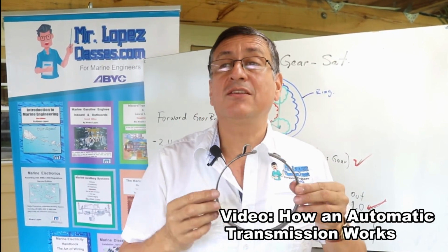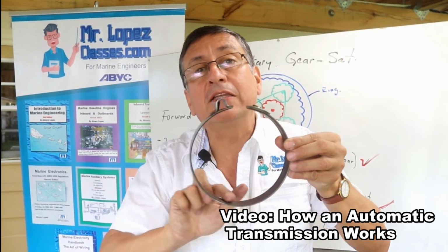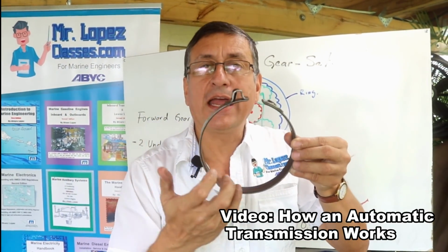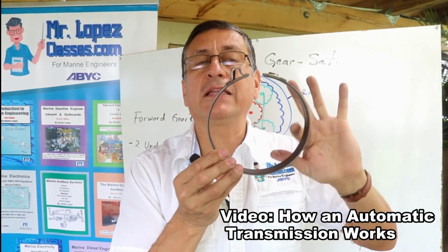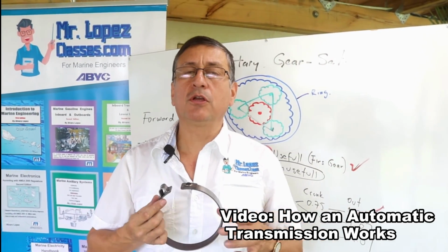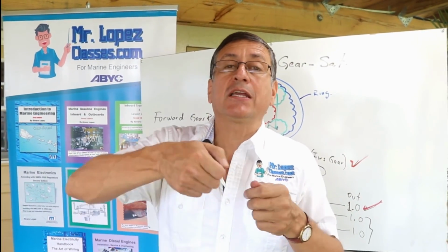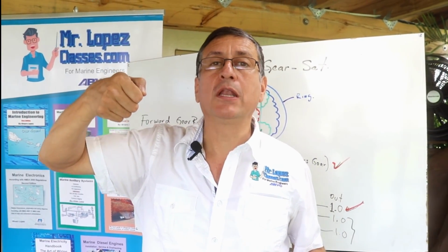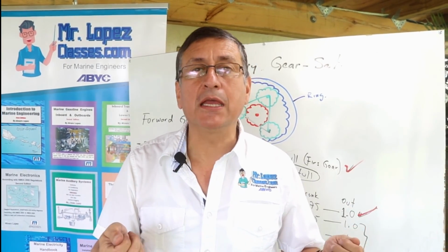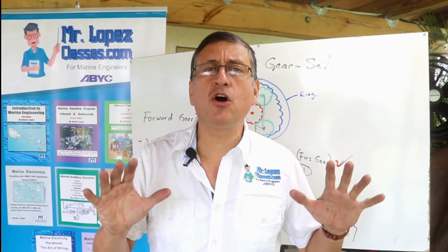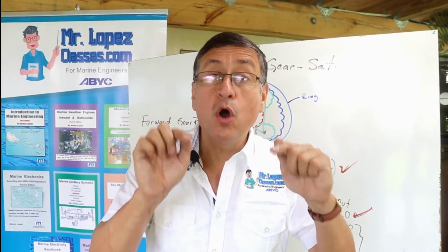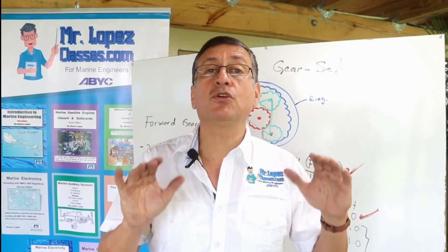And once again, the secret is the friction material and the quality of the oil. If the oil is dirty, it erodes the friction material. The enemy of that friction material is water. For that reason, you need to periodically check the color of the transmission oil. Verify if the color becomes brown or milky. You need to immediately flush and replace the oil, and verify where the intrusion of water in the transmission is. The enemy of the transmission is the water.